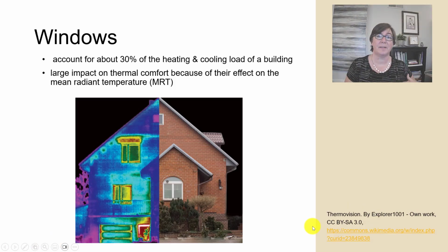In addition to this heat gain or loss through the windows, which adds to the heating and cooling load of a building, windows have a large impact on the thermal comfort of the people inside your home because of their effect on the mean radiant temperature. We're going to learn more about that later in this course. But just remember the last time that you were seated next to a window on a cold, cold night, and you could just feel that window sucking the heat away from your skin. That's what we're talking about with mean radiant temperature and windows.